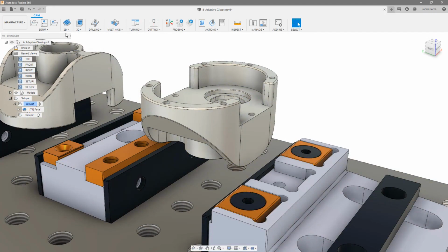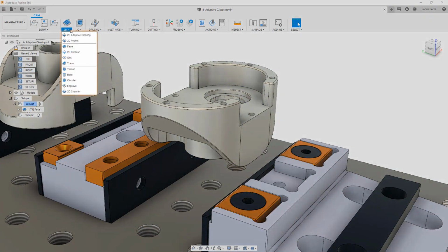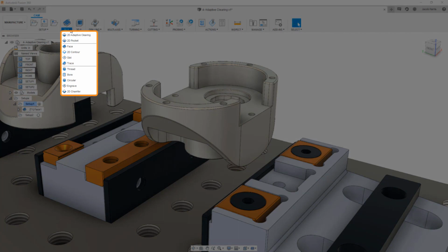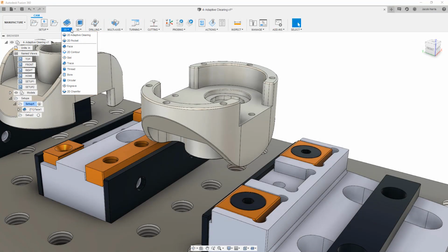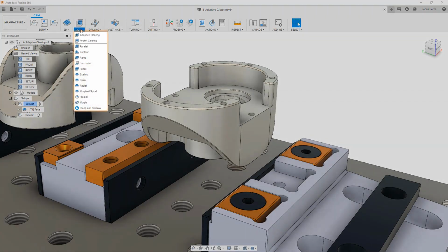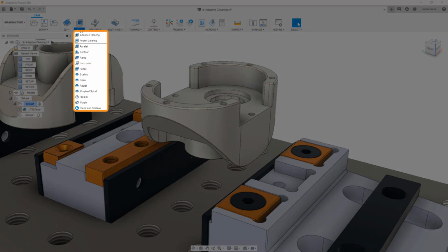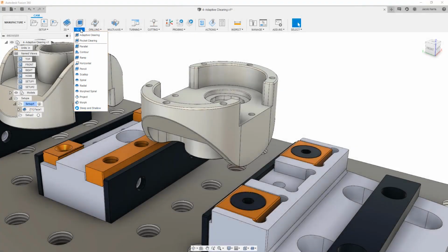You will see all milling operations in Fusion are separated into 2D and 3D strategies. 2D strategies are used for prismatic or 2D features and are driven solely from contours. Therefore, all 2D toolpaths require some form of contour selection. 3D toolpaths are for 3D features and are driven from the model surfaces. As a result, 3D toolpaths require no selection to generate. However, 3D toolpaths can be contained using a combination of boundaries and height containments.